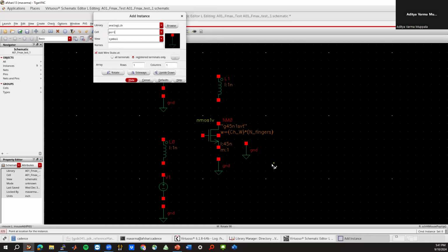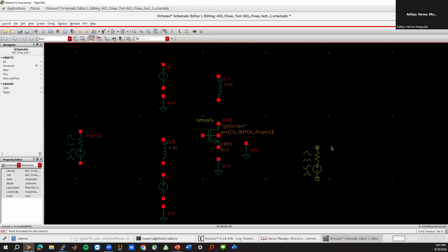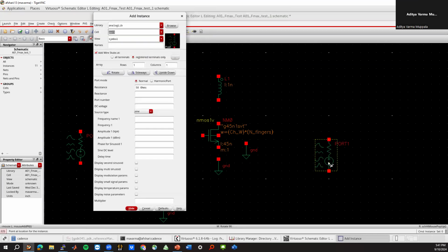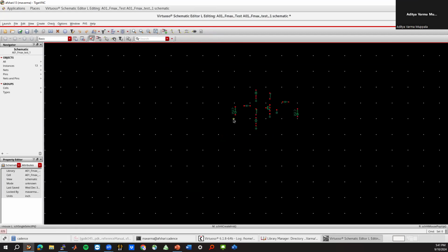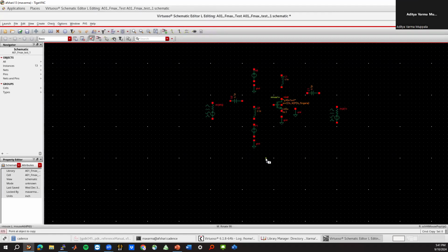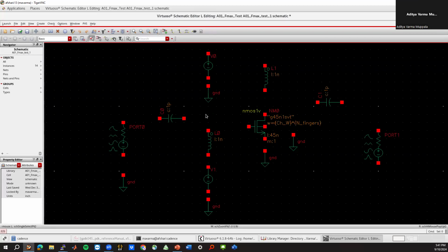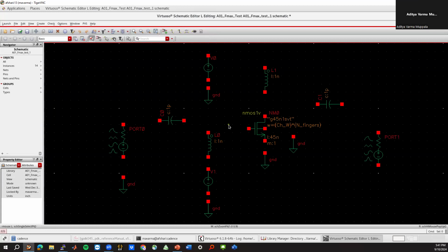And then I want ports. We need 2 ports. And I also want some caps. If I click the center mouse button, it rotates it. Just place one here and one here. Okay, so I hit C, and then I click and drop here. So C just copies an element. It's very different from general Windows, which is something you have to learn, I guess.